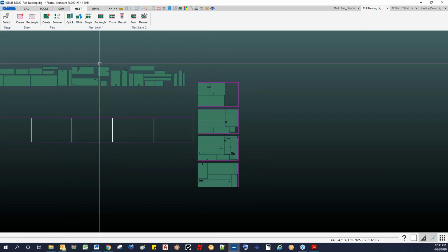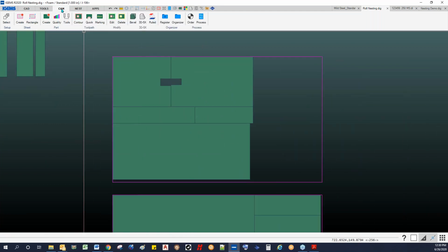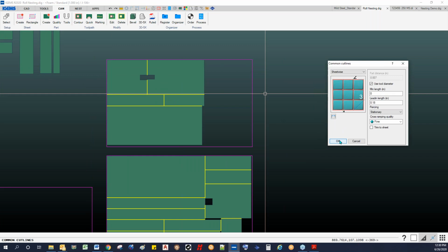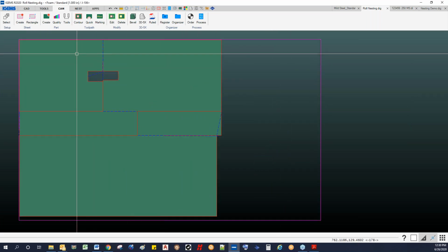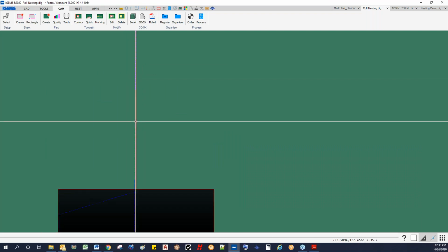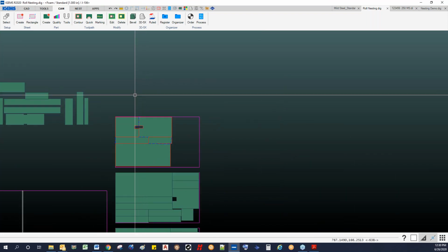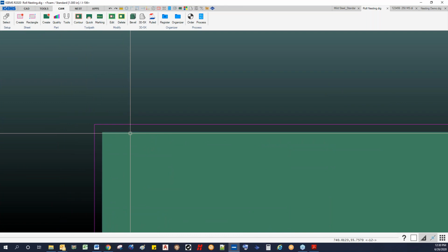And then to actually add the common line cuts onto here on our cam tab, we can click on here and go into the toolpath area. And we have the option for common. And basically click on OK here and select the sheet. And it puts our common cuts here. So it'll do one cut to separate those two pieces there, and then we can do the same thing for the other sheets.